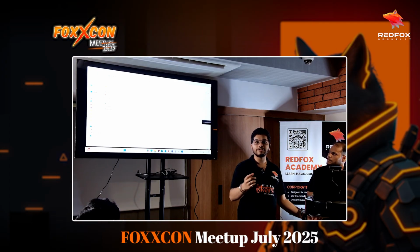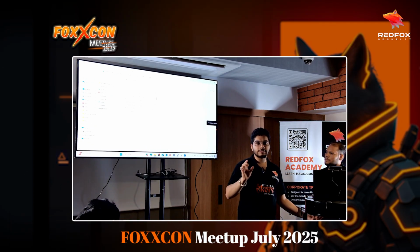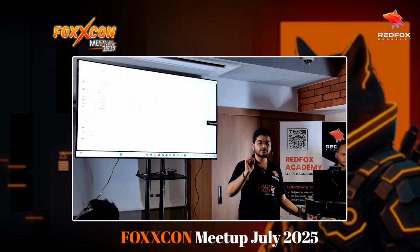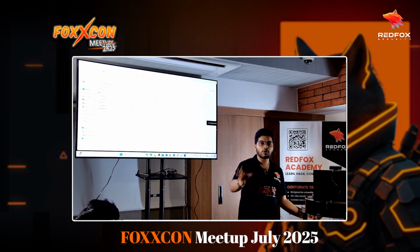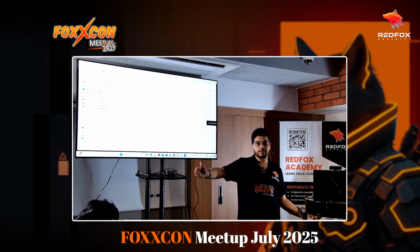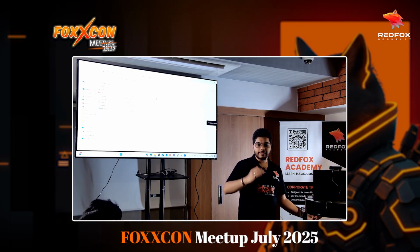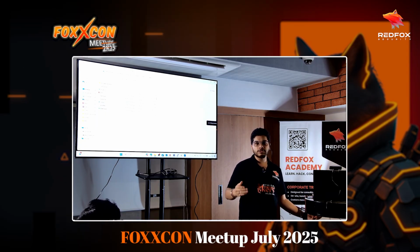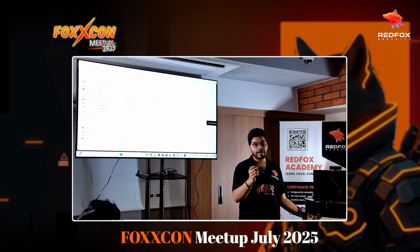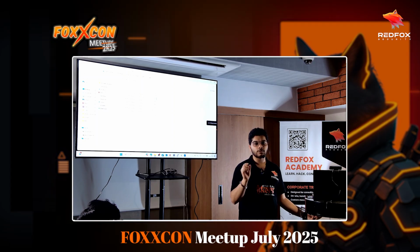Asynchronous means it doesn't have a clock. Generally, whenever you are talking about serial communication, there is a specific port that spits out the clock used by the device, so that the rate of transmit is known. If you don't match that, your data will not be decoded properly. That's why in most communications you will find a serial clock as a port. Like we saw transmit and receive here, there will be a serial clock.